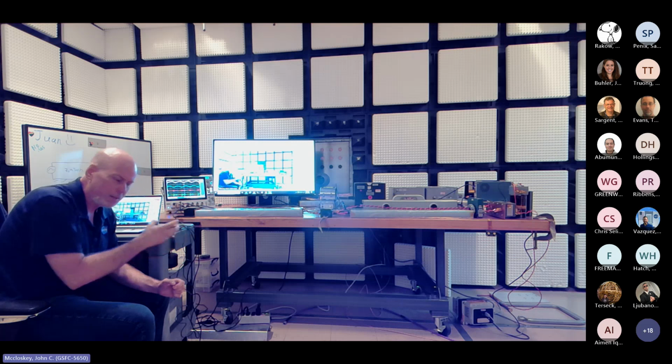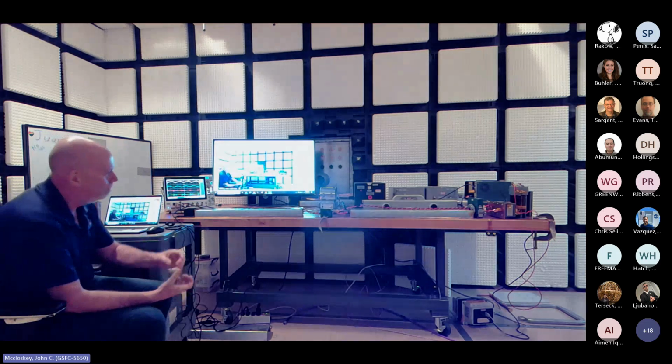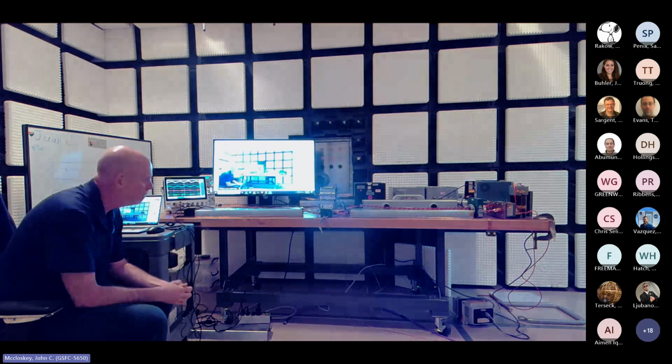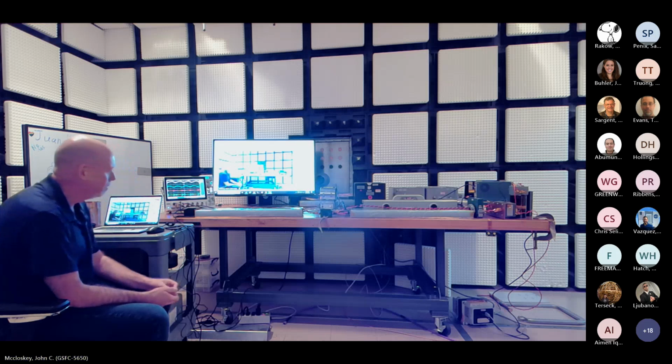That's a test and measurement thing, but you're usually doing tests and measurements, primarily with these test methods, to check off a box, but don't tell anybody I said it that way. You're testing to determine, does your box meet its EMI requirements? And if it meets them all, great, you're done. You move on to thermal vac or vibe or wherever, or integrating onto the spacecraft, whatever it is you're doing. If you do see an exceedance, then at least in principle, you should be going to the next step of diagnosing the problem and fixing it, or determining, is this really a problem or not? But you measure what you measure.